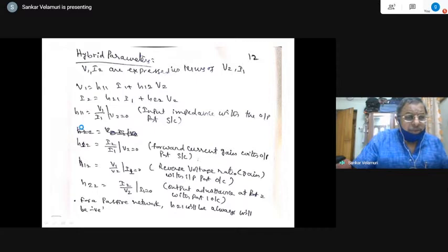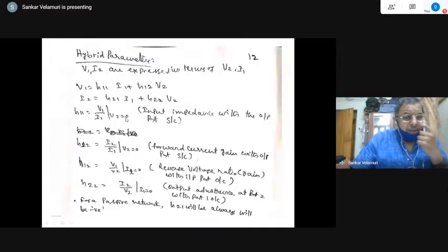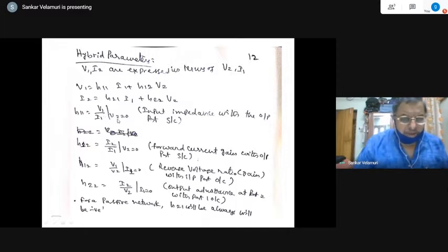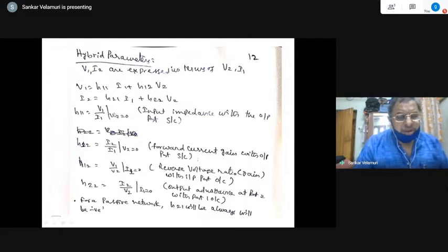Now you can see in the transmission parameters also you have A equal to V1 by I1, the source impedance, which is based on the load impedance that is being connected. So this is a typical case where V1 by I1 is the source impedance when port 2 is short circuited. So conditions differ. That is where there must be some clue in finding the one-to-one relationship. That is beyond scope here because time will not be sufficient. That is an independent topic. We would need an extra two-hour slot or maybe more, because for all two-port network parameters, a one-to-one relationship can always be obtained.